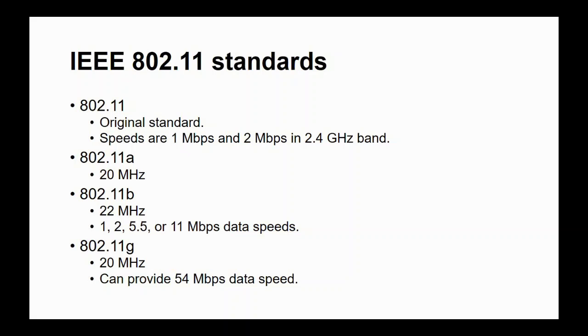Even though the 802.11b standard can run at a variety of speeds, 1, 2, 5.5 or 11 Mbps, and the newer 802.11g standard can run at speeds up to 54 Mbps, the differences occur in the radio frequency modulation scheme used, but the channels are identical across all the applicable 802.11 standards.